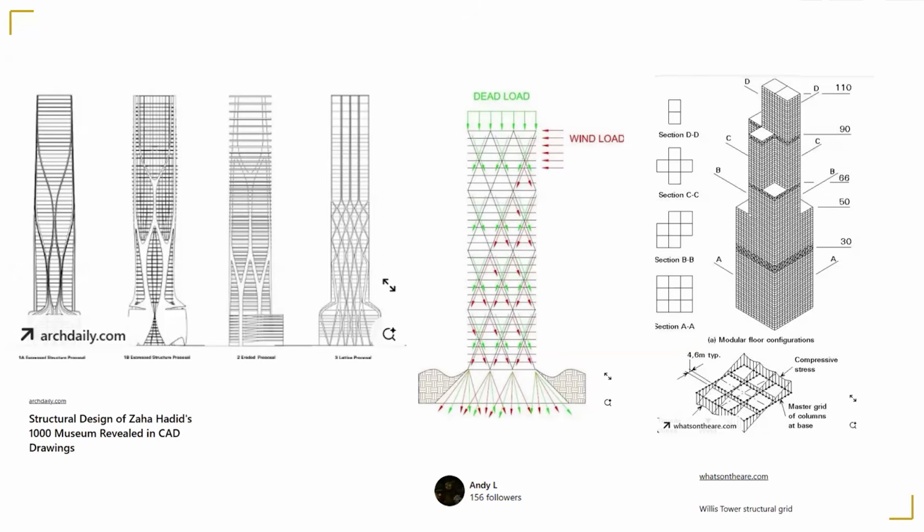So all these start from 9 tubes and gradually reduce the tubes as you go up, because you don't need them, right? Everything is optimized at the top level, not one beam, one column, one reinforcement. Many engineers think, I'm going to reduce the reinforcement in my beam. Instead of 4 bars, I will use 3 bars. That's no optimization. This is real optimization, when you optimize the form, when you think about the whole thing, and then you create something interesting.